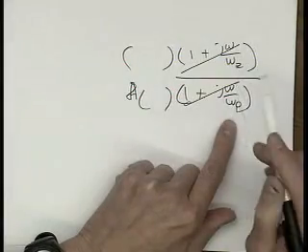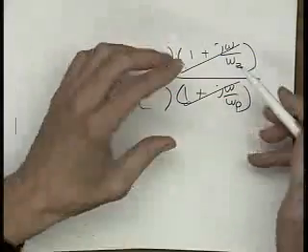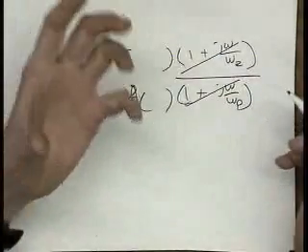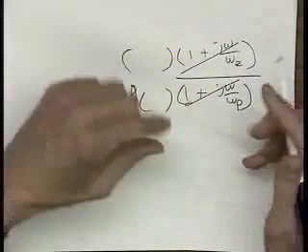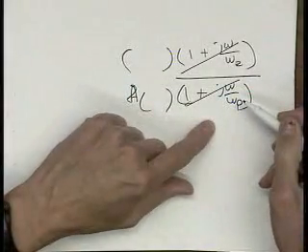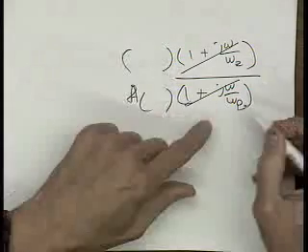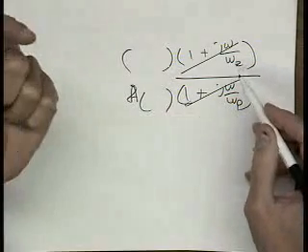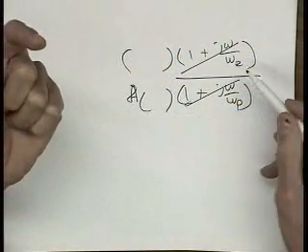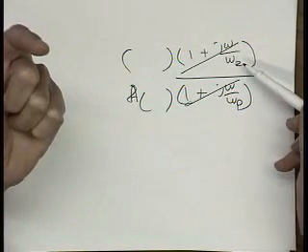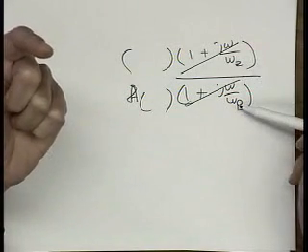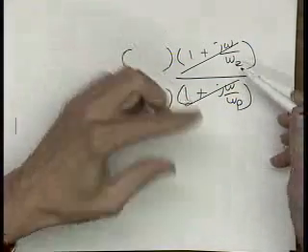What SPICE will do is calculate the roots of these polynomials to the best job it can through its little algorithm inside for root solving. But there's some error at which it will declare that it has found a different zero and a pole, and so it'll show up.